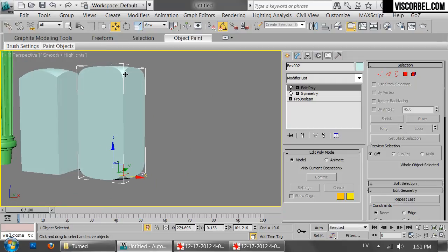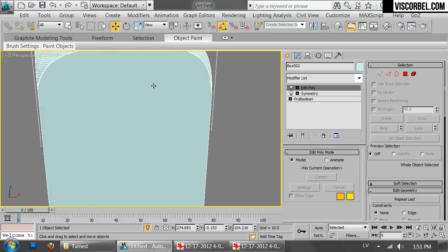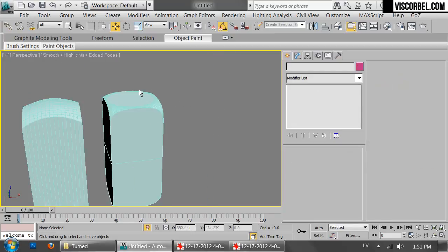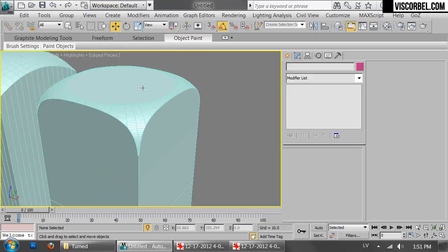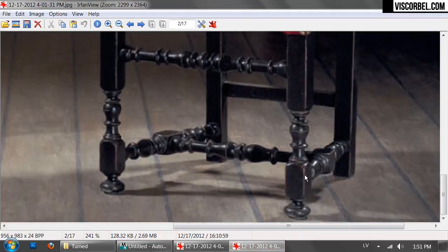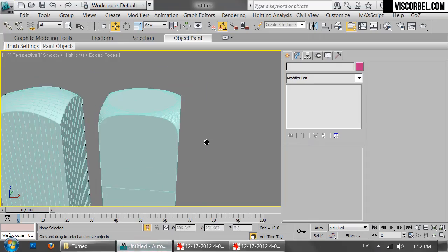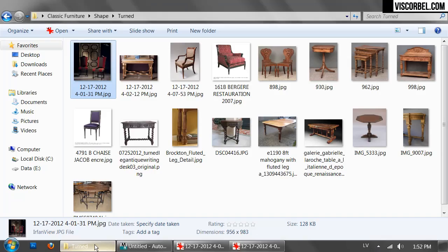If you want a larger chamfer, you have to go in manually, and that's a bit tricky. Then you would probably use a low resolution profile and edit the resulting mesh manually to add some support edges and stuff like that. But most of the time, these edges are pretty sharp, so this works well, and it's pretty quick as well. Right.